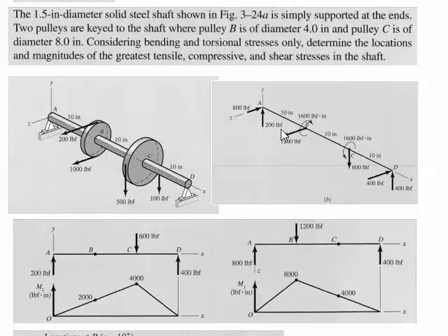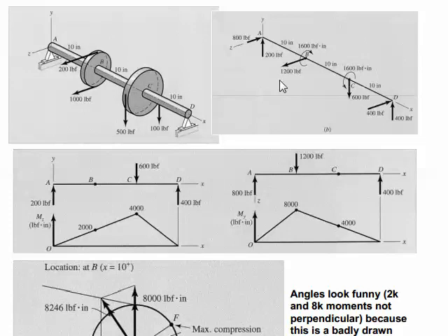Now, drawing shear and moment diagrams of this geometry. First of all, in the XY plane, where this 200-pound shear force will get us started. We move across. This load does nothing in this shear diagram. We move across to here, and that 600-pound load is applied, and then finally we have the 400-pound reaction in the vertical direction. And this is the loading diagram.